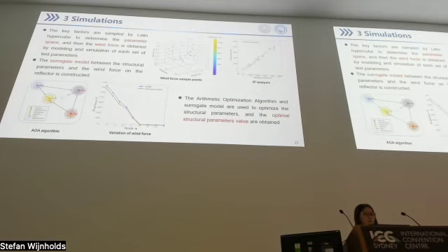The key factors are sampled by Latin hypercube to determine the parameter space, and then the wind force is obtained by modeling and simulation of each set of test parameters. The surrogate model between the structure parameters and the wind force and the reflector is constructed. The arithmetic optimization algorithm and the surrogate model are used to optimize the structure parameters, and the optimal structure parameter values are obtained.